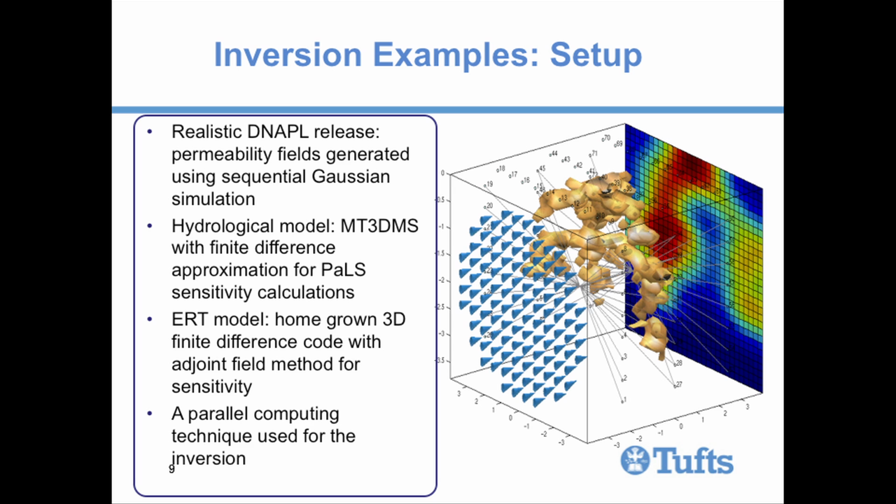This is just two slices. The data that you get is three strings of cross-gradient ERT, and then down gradient, you would see this blobby image in the best of all worlds, representing how much of this bad stuff the nominal groundwater flow picked up. You almost see the shape here, which certainly constrains the problem. It's reflective of the general geometry of the structure, but in fact, if you use the right physics, which is flow and transport of multi-phase flow and transport through heterogeneous media, through the heterogeneous earth, porous media, you can do a bit more.